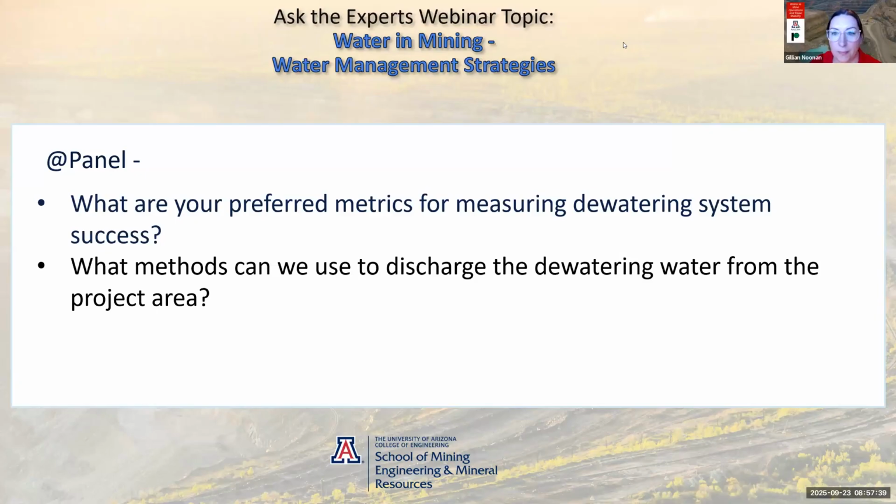Good point, Paul. Yeah, the metrics for dewatering tend to be easier. In iron ore projects, for instance, a lot of people just track the drawdown and try to get it always 20 meters below the lowest pit floor at any one time. So if there's a rapid advancement of the pit floor, let's say by 6 or 7 benches in 6 months, then you have to get ahead of that. So there's some good examples of that in lots of places.